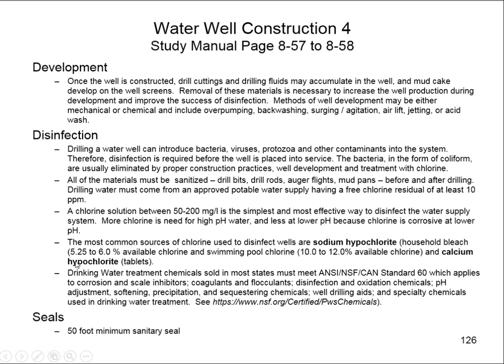The calcium hypochlorite is another source of chlorine, but as tablets, they don't always dissolve completely. So you might have some variation in the percentages of chlorine. And then finally, you need to put in a 50-foot minimum sanitary seal. And this is pretty standard across the US, although there's no standard. But this is often what is practiced in most places. There's no national standard on well construction.